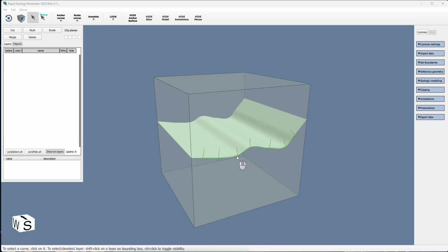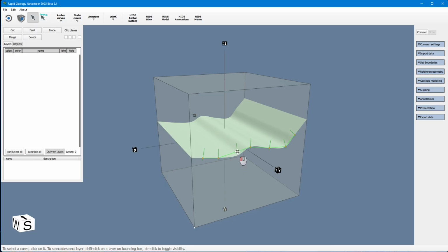You select the point by left-clicking on it. Then it can also be moved. When the point is selected, you can choose to add point. That will add an extra point on each side of the selected point. Here you see the new points. Let's select this one. You can delete the point you selected, and you can cut the curve into 2 pieces by selecting the cut position and split. Now you have a curve here and a curve there, which you can manipulate independently or delete one or the other.